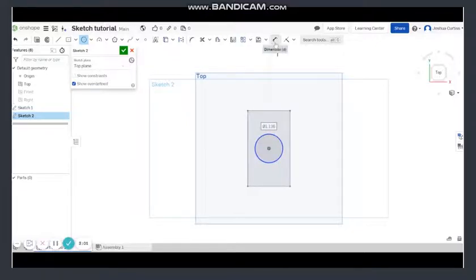Just like the other one, we're going to click this dimension tool. And instead of clicking a side, since circles don't have sides, you're going to click the edge, drag in, and here you'll see the current dimension of it. I'm going to set this for 2 inches. Oh, actually, that's too big. Sorry. Let's do 1 inch. There. Okay, much better. And that's kind of how you do those 2 shapes.